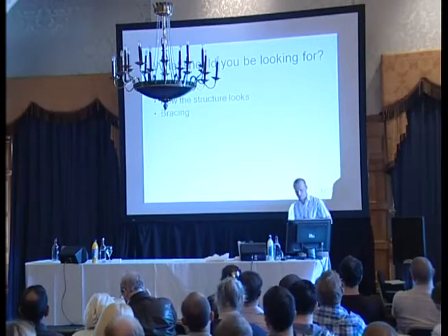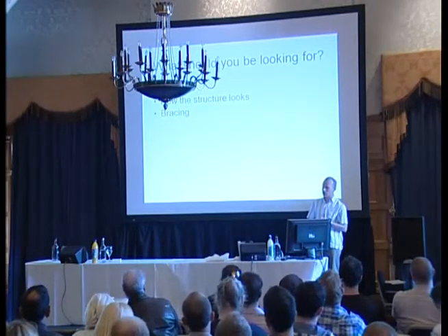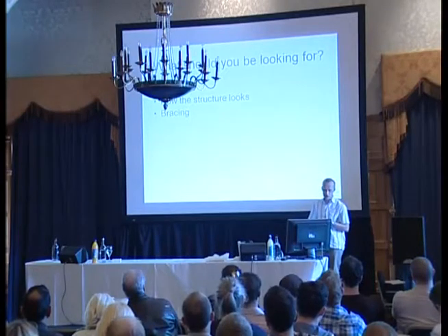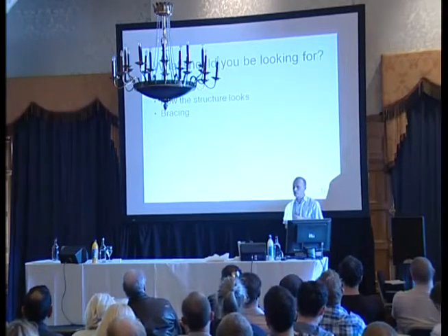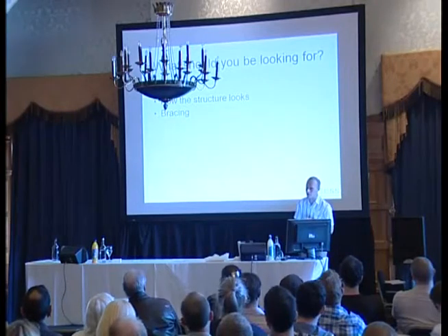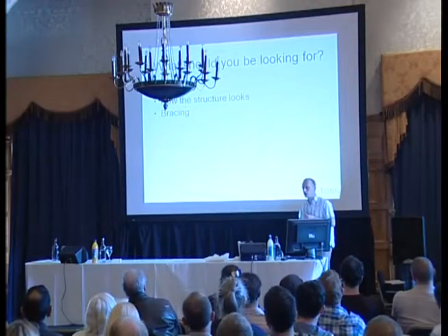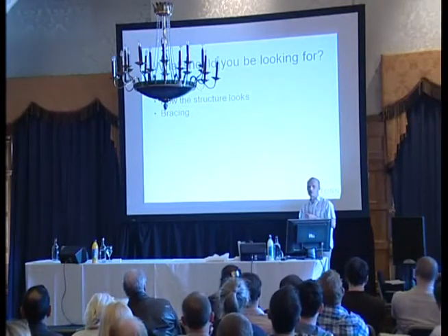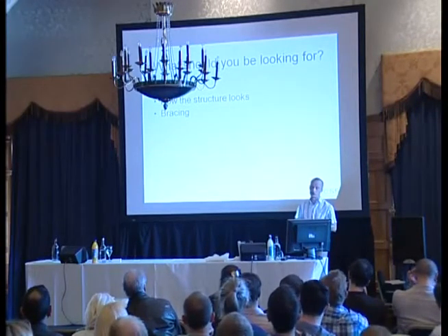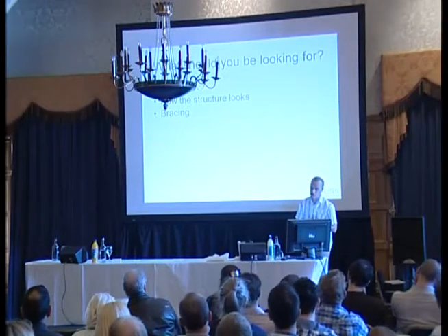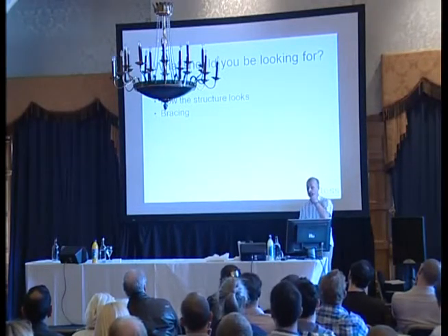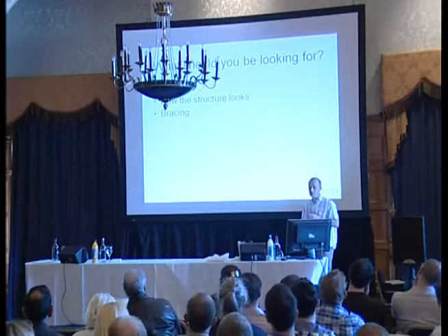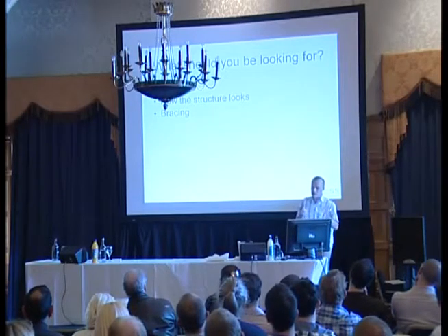Bracing. Now, there's an interesting one. Certainly, when you get into scaff stages, what bracing should be there, what shouldn't be there? Well, again, ask for the drawing. The drawing should be able to show you what diagonals there should be through the base of your stage to ensure that you've got a safe stage. There should be, in any marquee, wind bracing in most clear spans every fifth bay.